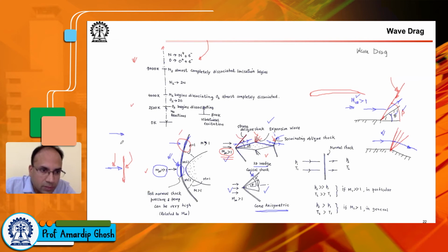So the wave is somewhat like this, and then we say this is the oblique shock interaction. Because of this difference in interactions at different positions of this wave, the flow field behind a normal shock wave is always subsonic. The flow field behind an oblique shock wave, for the weak oblique shock wave, is such that a subsonic or supersonic situation can arise. But in most cases in nature, we have the weak solution of the oblique shock, and the flow field behind the oblique shock is supersonic.